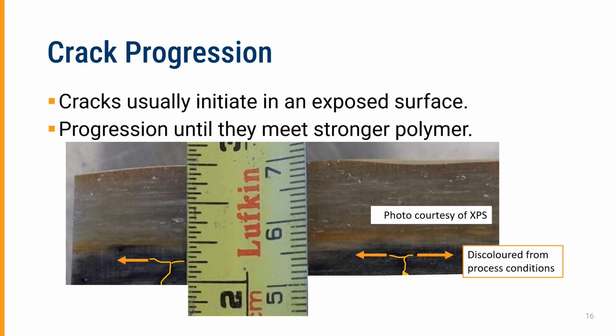So the crack literally turns and spreads out. So this actually produces a large number of planar indications that a lot of people would think of as defects in metals, but that it just really indicates crack depth in FRP. We'll talk about that in the NDE video.